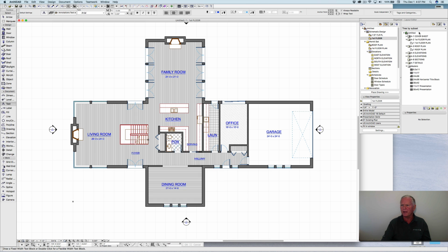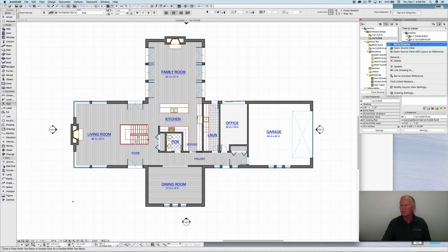We're going to do that by having this side over here on the layout book and this side under the view. And that's our first floor that we've been working on. That's highlighted right there. What we're going to do is look over here, and we've already got some sheets set up for the project. A2 is set up for first floor plan. So you see that's a view right there. That's already got a first floor plan on it. It's not the right one. So we're going to click on that, right click, and go delete.